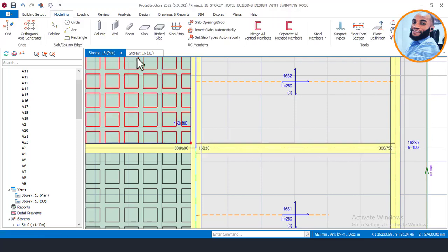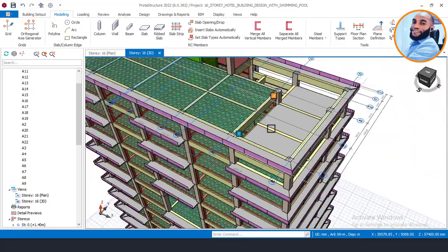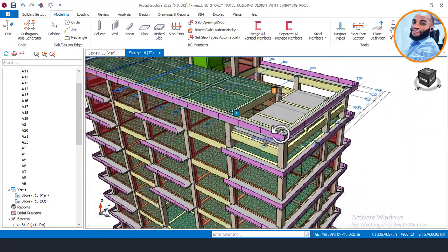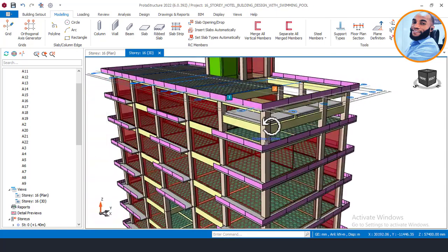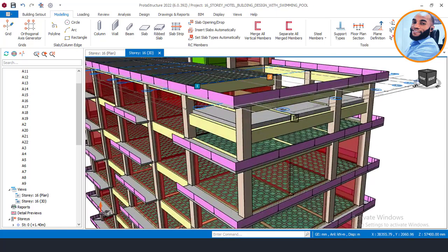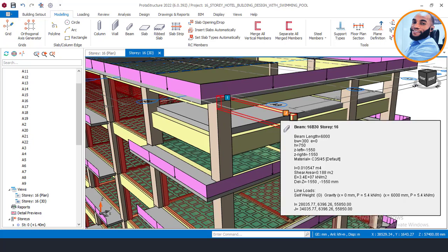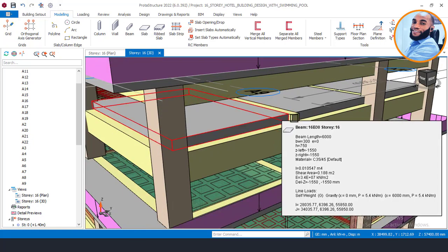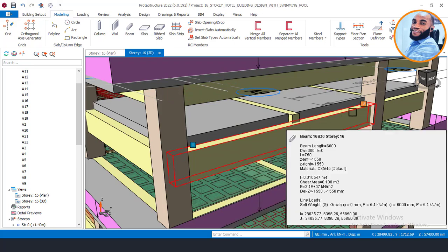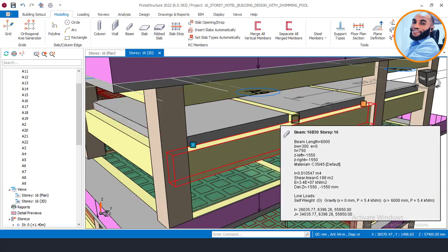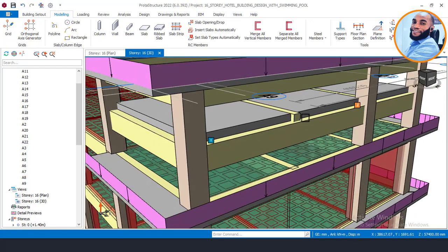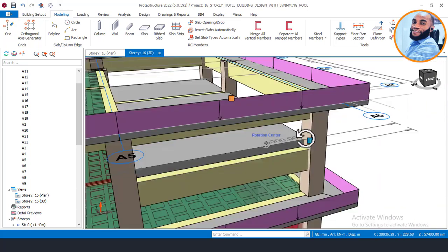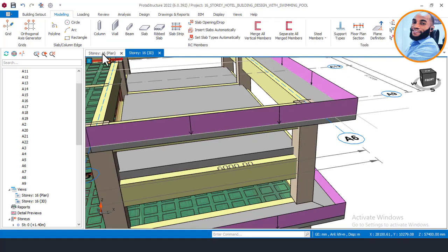And then if you come to the 3D view right now, you can see what we have got so far. This is what we have just got, which is very perfect, as you can see. And we will also have to drop down this beam. This beam will drop down again by 1700, I can see here. Although this is okay because there will be a retaining wall on this area, so this is perfectly okay. It will anchor itself partially on the beam and also on the retaining wall. Okay, that's fine. So right now we will go all the way down to the plan view again.